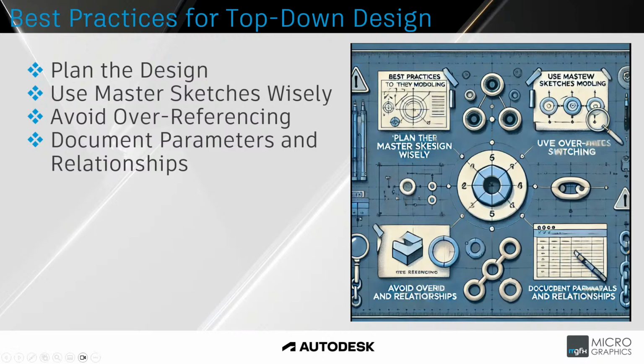Avoid over-referencing. Minimize the dependencies between components to prevent circular references or slow updates. Document parameters and relationships, where we use descriptive names for parameters and sketches to improve the clarity and the collaboration.